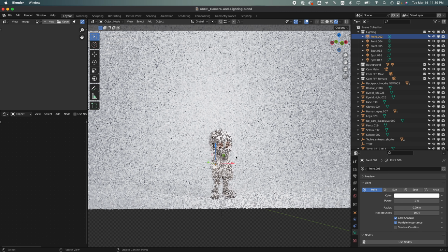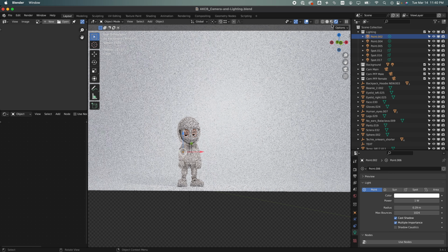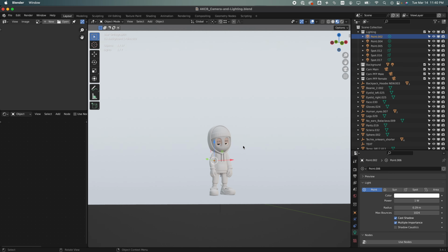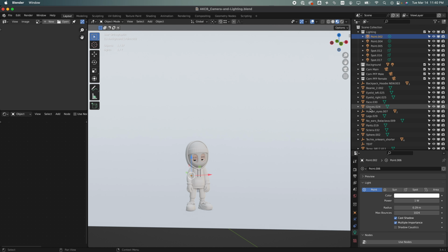Okay. One important thing I forgot to mention before even lighting was how to move things around. So first up, for setting up the scene, you're moving your camera around. I'm going to go back to material preview. You're moving around. Let's say I want to move something. I don't know what it could be. It could just be this point light. We have this list of options here to the left. We have select, and then we have here move, which hotkey is G.